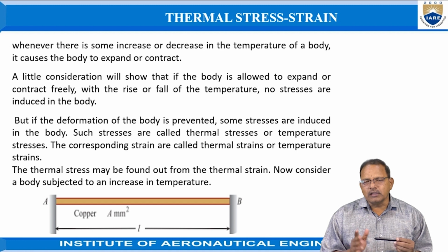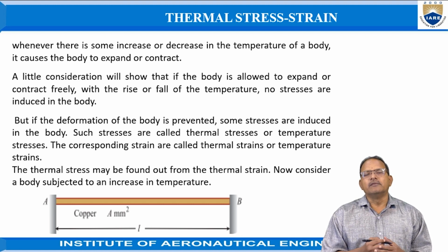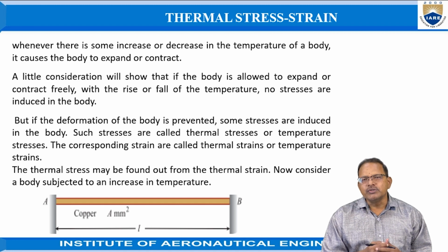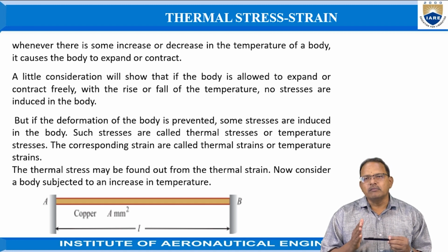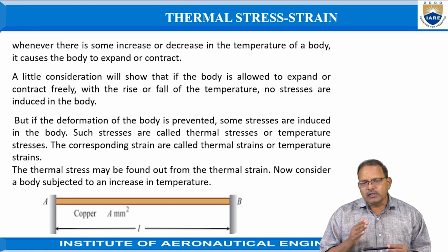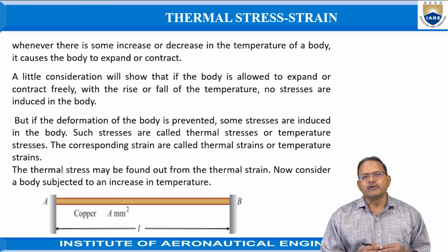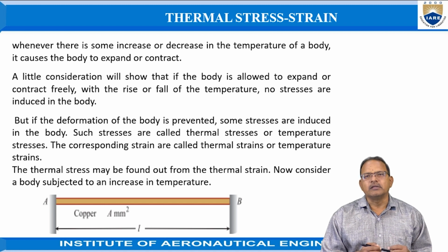Now when supports are kept to prevent deformation, when the temperature of the object is increased from 0 to 50 degrees, then stresses are induced in it. The supports exert reactions on the object to prevent its free expansion as the temperature increases. Hence, compressive stresses are developed in it.